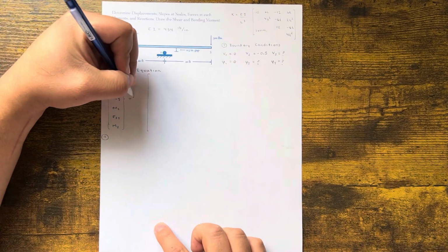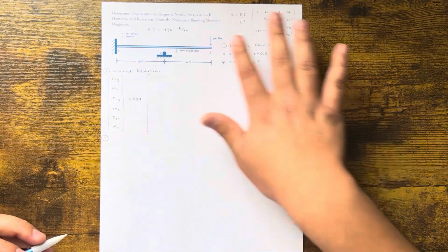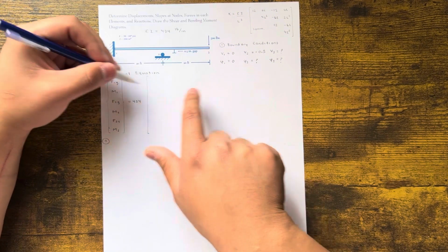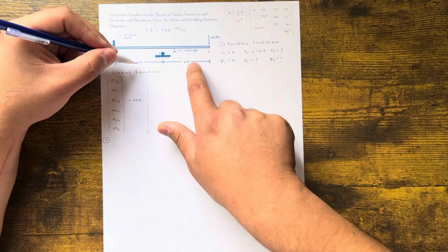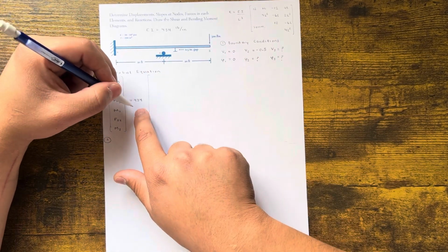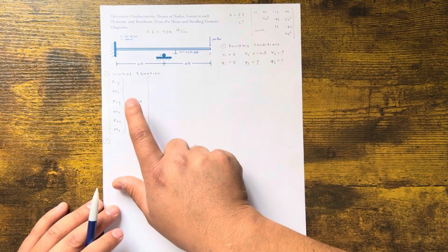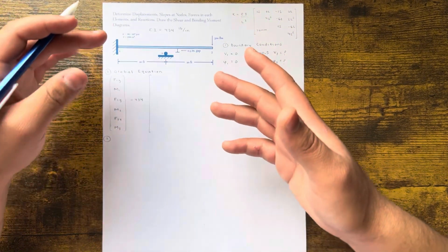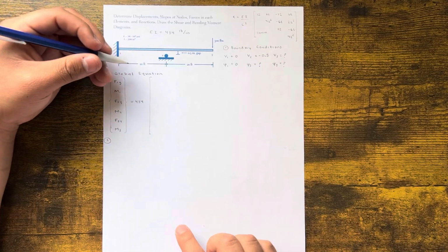We're gonna put 434 right here, and that number should be the same for every element. In this case, because they're the same length, we could just factor that out of the global stiffness matrix. If not, this could have been 20 feet, this could have been 10 feet, so it's not recommended to do over L cubed. It's better to put the L cubed in the matrix and multiply L to every single element, and you'll just have EI over here, okay? Just keep that in mind. They might trick you with that, but in this case, the problem's symmetrical. It's 20 and 20, cool, we're perfect.